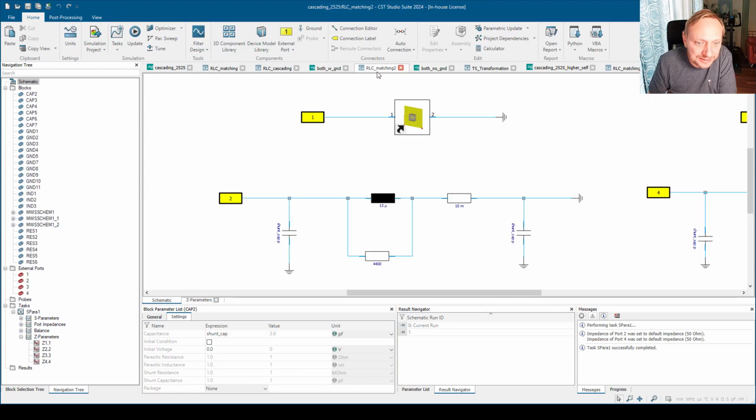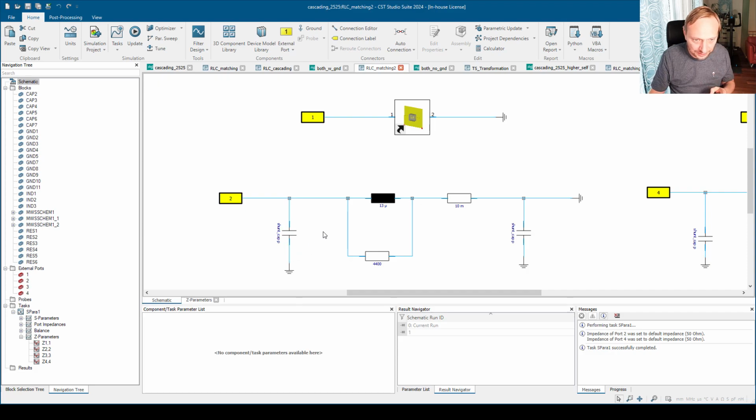So I can build a much better model by taking now, so we had 3.6 pico in parallel, and if we take 2 times 3.6 pico in series, basically, right? That's how the current can flow. It's exactly the same thing. So I take the 3.6 picofarad and put them at the beginning, like thinking this is the capacitance of trace 1 and trace 2.